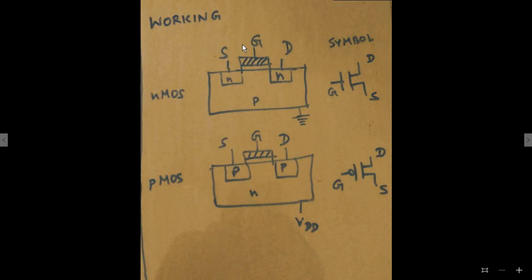So if we increase the gate voltage to high, what will happen? In the upper layer near the junction, holes will be settled because positive charge, high voltage, is applied. So under this insulator, because of these holes here, there will be an electric field created on this side, which will result in accumulation of electrons here because there are holes on the other side.